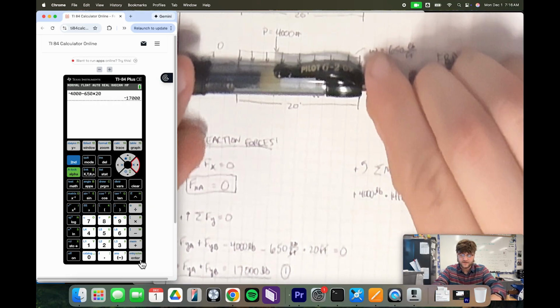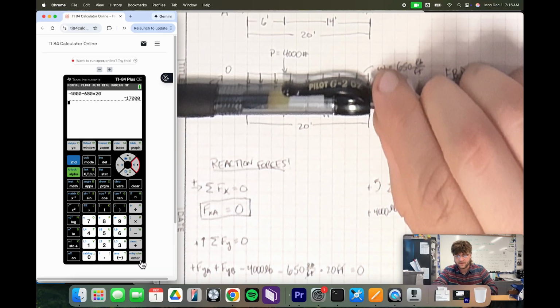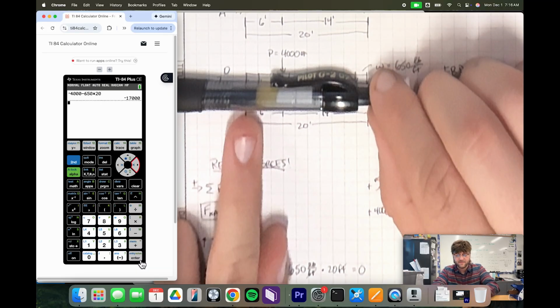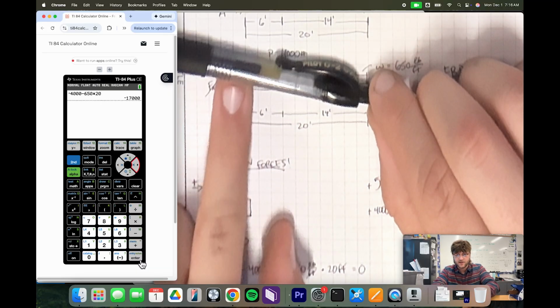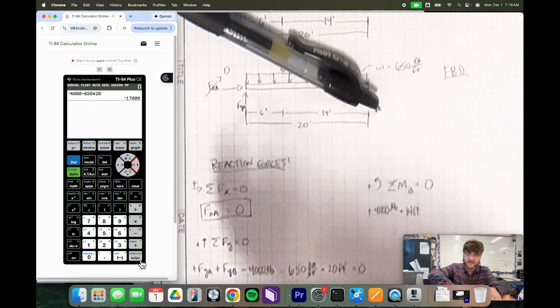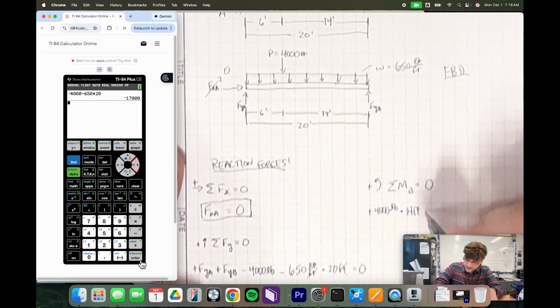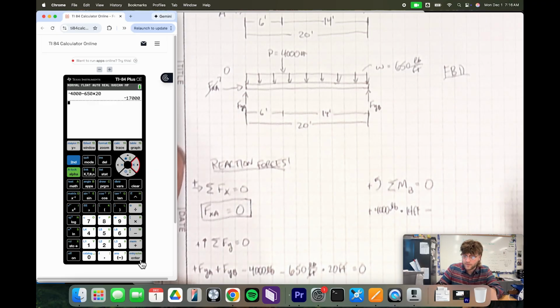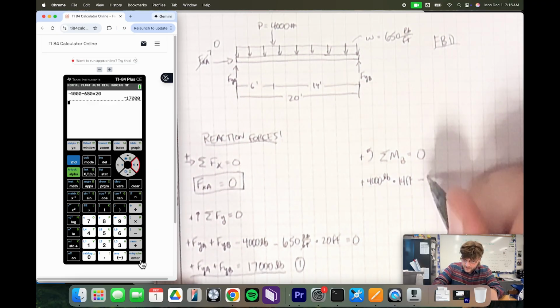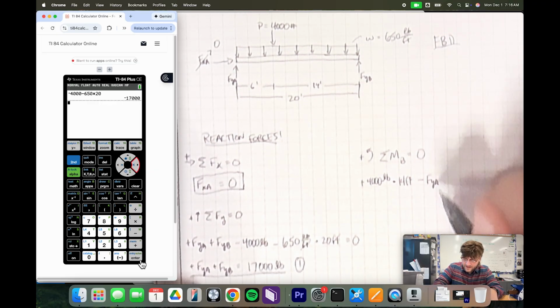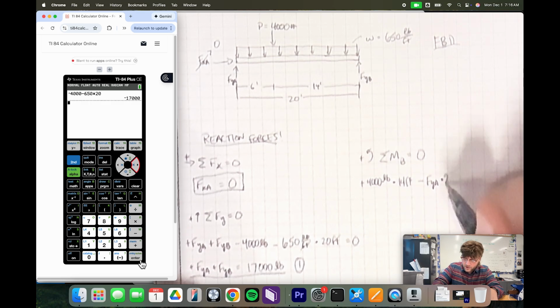If I put my pin here again, hinged on point B, and apply that force here, you'll see that the pin starts to rotate clockwise, just like the way of a clock. And so that's why we've got the negative moment here for this one. That's going to be equal to FYA, multiplied by 20 feet.